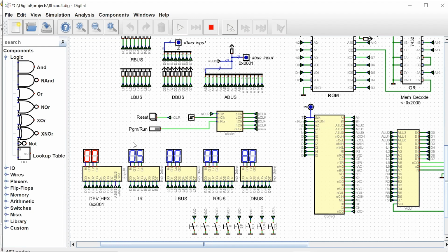Now we've loaded the 5 into our instruction register, and we're also starting the read of the data, which is the hex 80 we can see here. We can see that our A in signal is raised, and we will just clock that in. Okay, so that's been executed. Now we're at the next instruction. You can see our program counter is advanced to location 1. So we executed that load instruction.